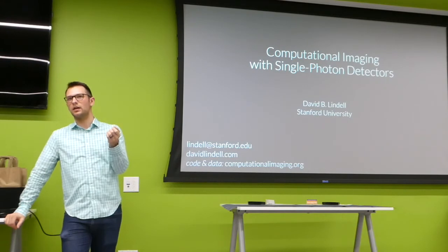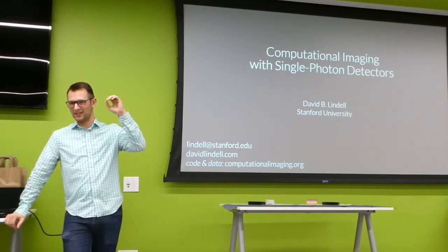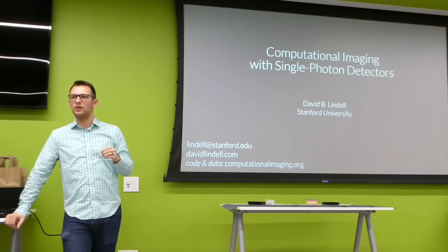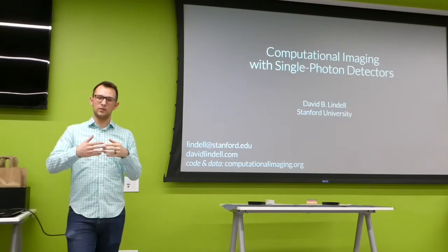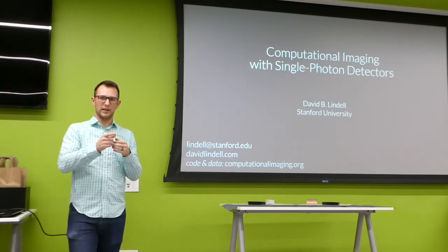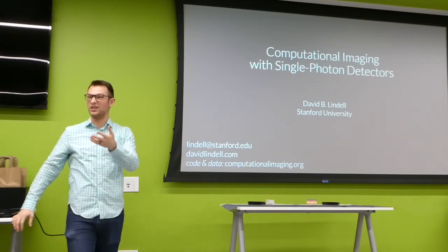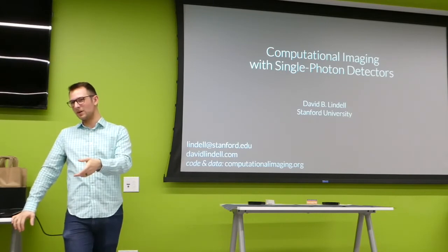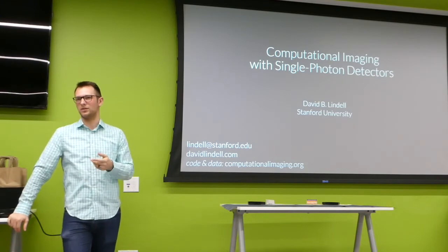I used a different technique in this case, which made the reconstruction easier, and that was that each speaker transmitted a signal independently. There's been some work in radar where they used a phased array to do through-wall imaging, and they actually scan that way. It's a similar problem because you have the same sort of specular reflections at radar wavelengths as you do for audio wavelengths. So I think the answer is yes, you can do it.